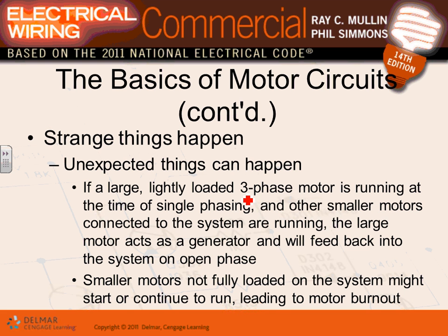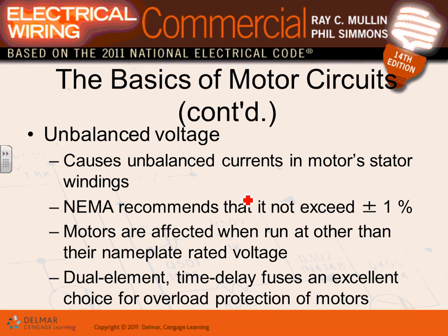So if you double the load on it, take this. If it's rated for 10 horsepower and right now you're only pulling 5 horsepower out of it, and if you single phase, you're going to double the current in it. When you double the current, you're still within the working parameters. Do you see how nothing is going to trip? So be aware of that one.